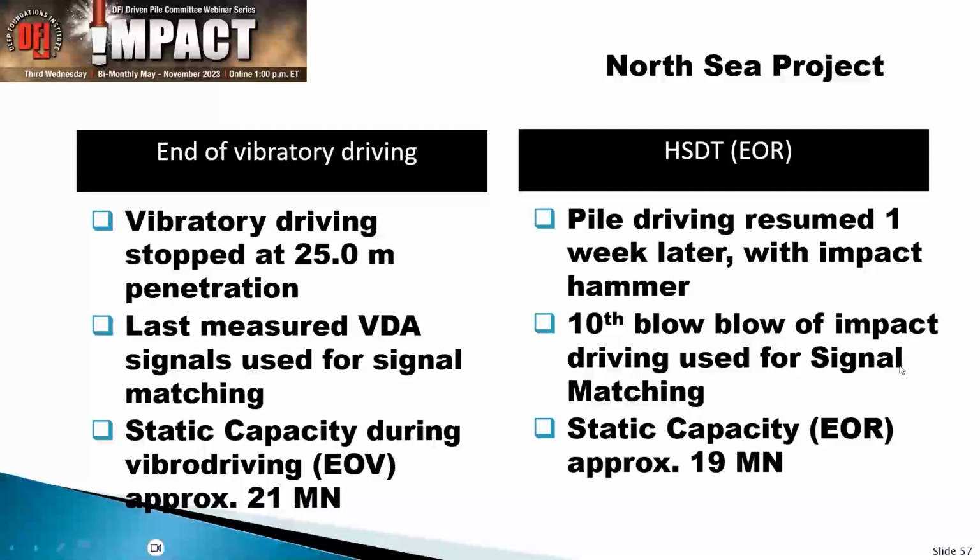And what you then see, your end of restrike, which normally is an acronym that you don't see often. Most of the time we talk about beginning of restrike. Suddenly you see that your capacity went way down and was very close to what we're seeing between the outcome of what we had on the vibratory driving and what we had now with impact driving. And that was important for a couple of things.